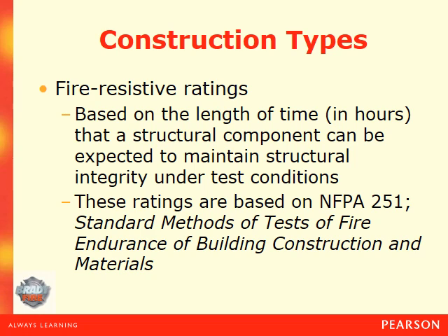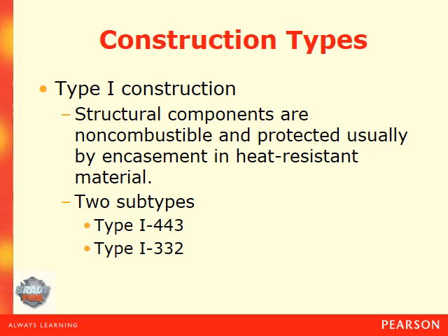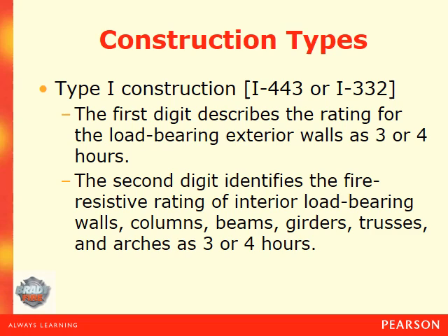So when you're looking at type 1 and type 2 construction, they probably have things known as firewalls or fire doors, and this is what they're referring to: how long will that structural element hold up to direct fire. And as I said earlier, in type 1 construction your structural components are non-combustible and protected by some sort of heat resistant material. I'm not worried about you knowing the 2 subtypes, that's just for your information.